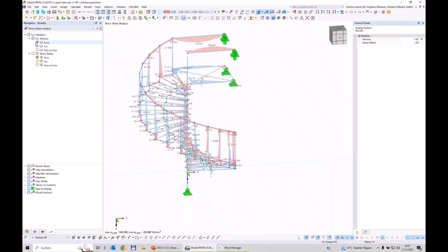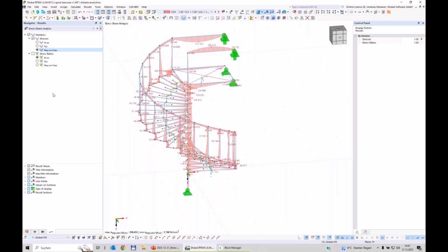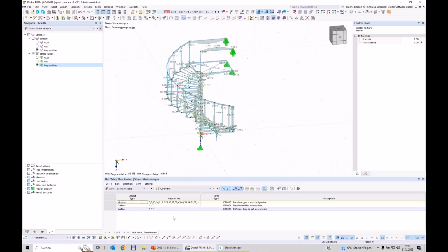Of course, drawing a multicolor picture on the cross section is difficult, but we visualize it then with such a diagram. So the program detects, most important information here on the bottom, we have a maximum stress of 203 megapascal. Here you get a picture of the normal stress, of the shear stress, of the equivalent von Mises stress, compared to the allowed limit stress. So you get the utilization of around about 90%. This is now also in the table below. And in the table below, you get at first from the stress strain analysis an overview.